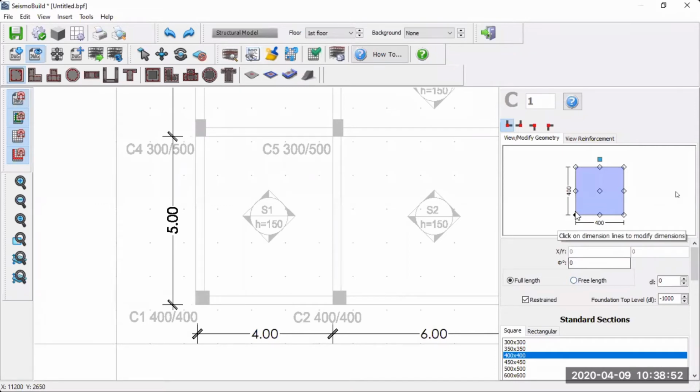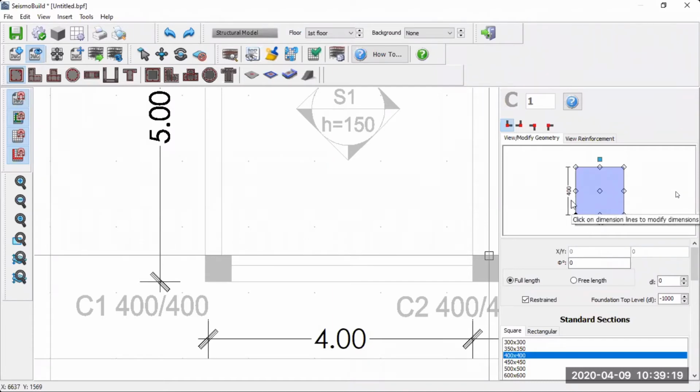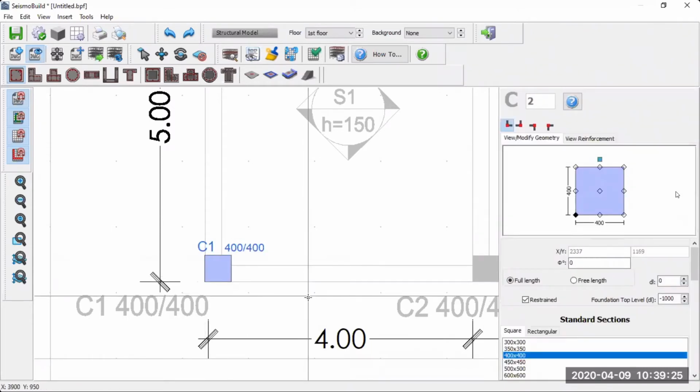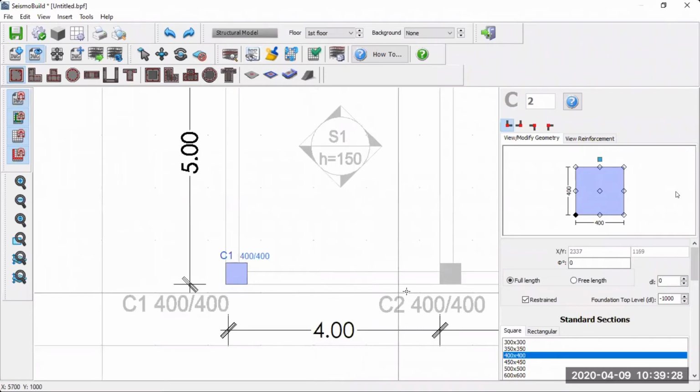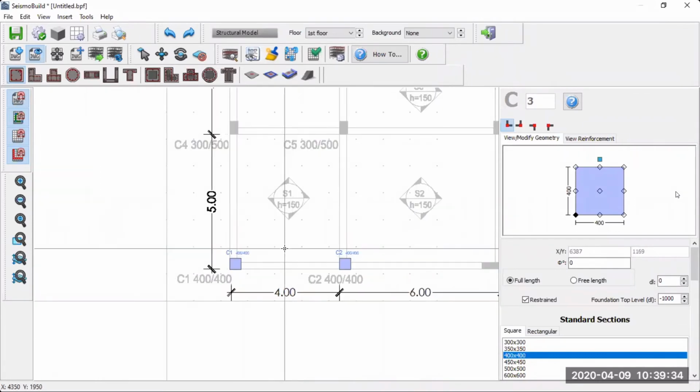All right. So when you insert, this corner must match exactly to the corner of these drawings. In this case, before you insert, try to switch on the snap to DWG function, the tool button here. You can see once I move my mouse cursor to here, straight away there will be an insertion point, because I already selected the insertion point at this left bottom corner. So I insert here and click insert. Straight away it inserts the column for you directly. Very simple. Similarly for C2 as well. I click this corner here, it will insert the column for me.